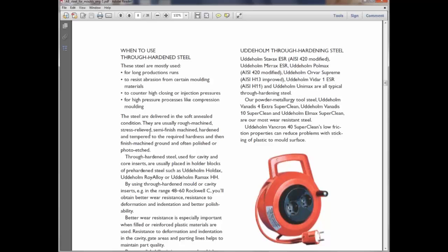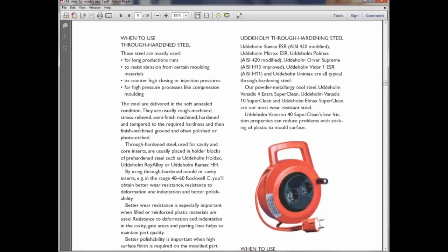Temperature variation is continuously happening on the mold. Because of that, we go for some alloying elements like chromium and tungsten. We use these elements in our molding material because they are heat resistant materials, so that the mold doesn't lose its strength at a very high temperature.